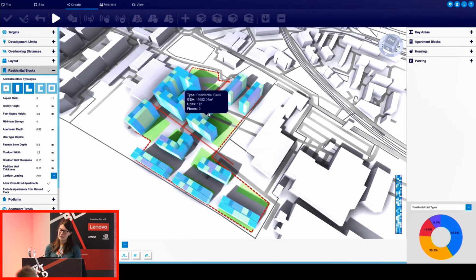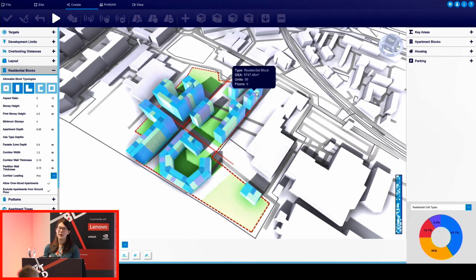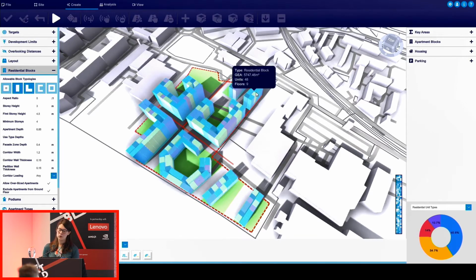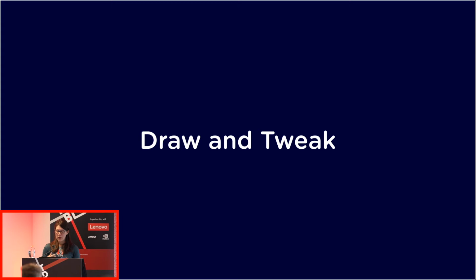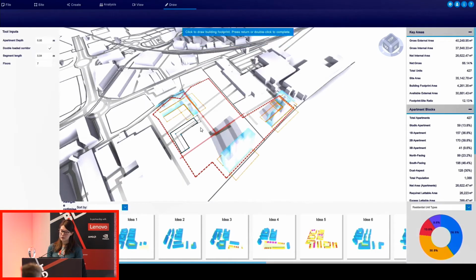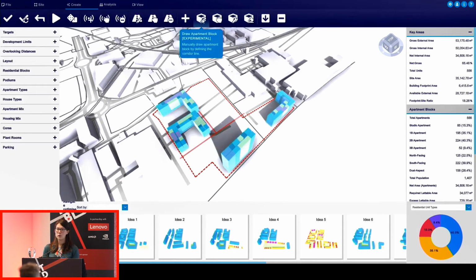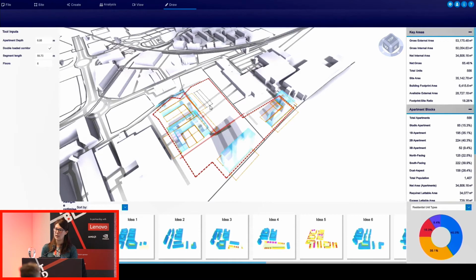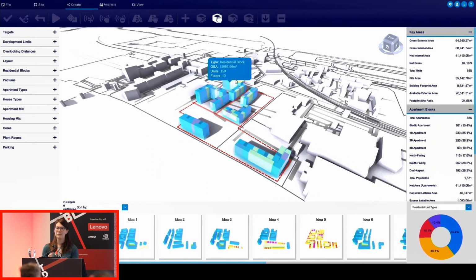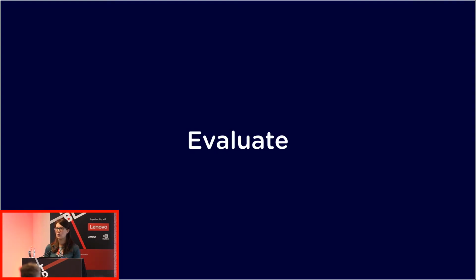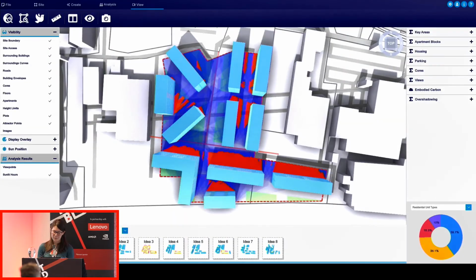And what it is doing is it's then generating possible massing options and optimizing to try and come up with the best or a good solution to meet the criteria that you're trying to optimize for. What's worth noting at this point is that each of those designs, every time it's generating an option, it's got engineering insight embedded within it. So it's placing the cores based off fire safety rules. It's sizing them based off early stage MEP, vertical transportation requirements. And so at every point, you have confidence that what you're generating should be buildable.